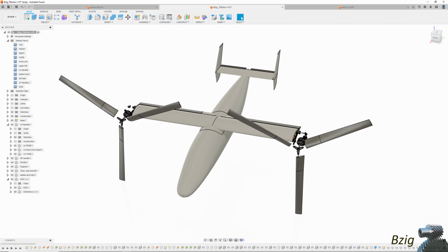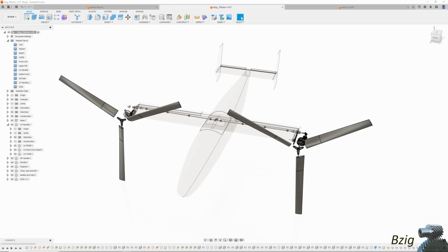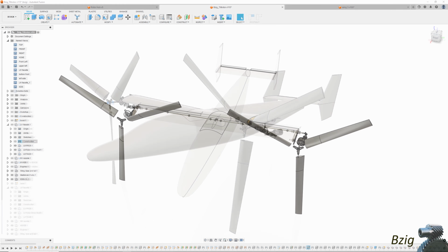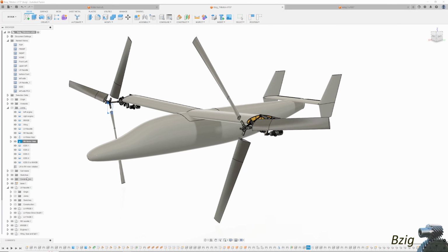But in tilt rotors, where the thrust must be placed far from the aircraft's centerline due to the size of the prop rotors, and where each side produces thrust roughly equal to the weight of the aircraft, it's essential that both side prop rotors always have power. The wing interconnect driveshaft is the means to provide continuous power to both prop rotors regardless of the operating state of the engines. If you think I just misspoke, I did not.